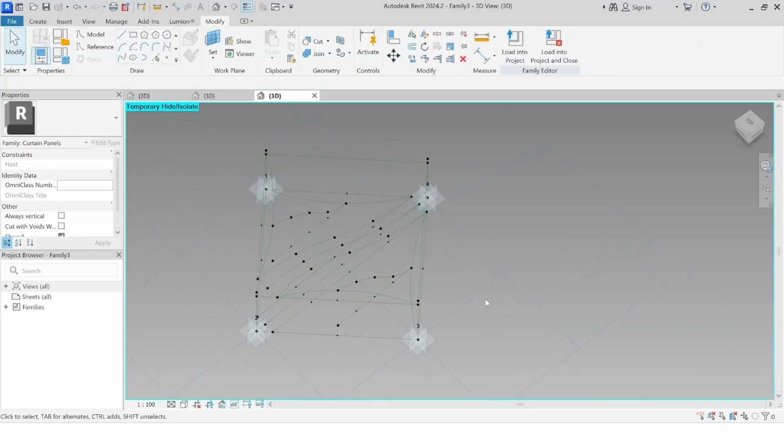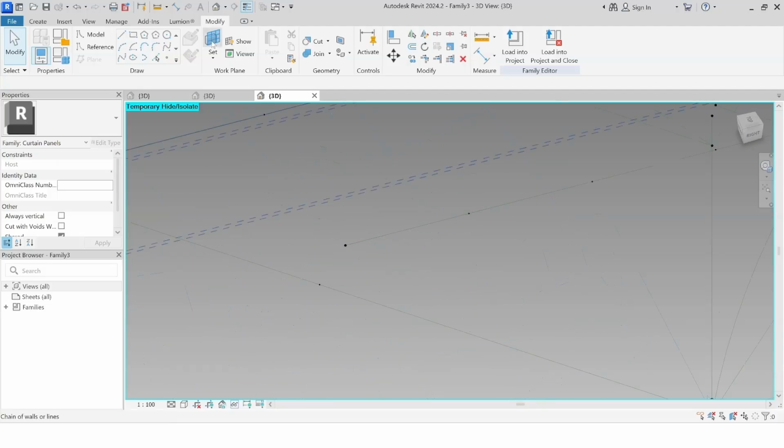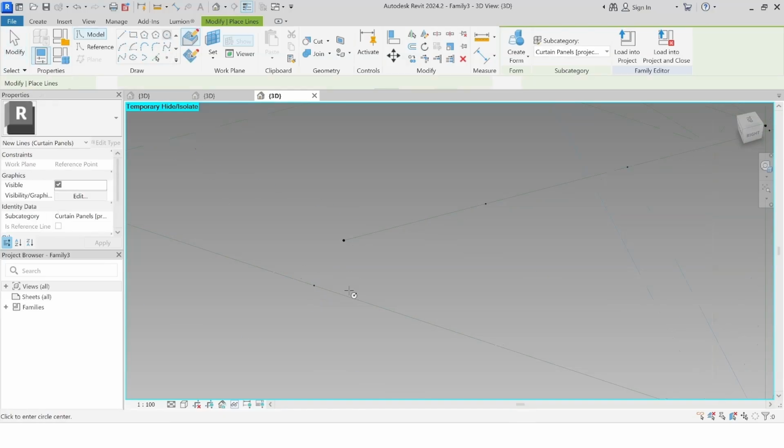And now the easy part is to create the outer structure, steel structure that fastens it. We'll start by selecting this plane right here, creating a small circle of about 150, something like that, 150.